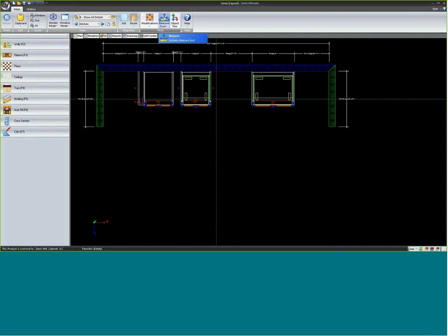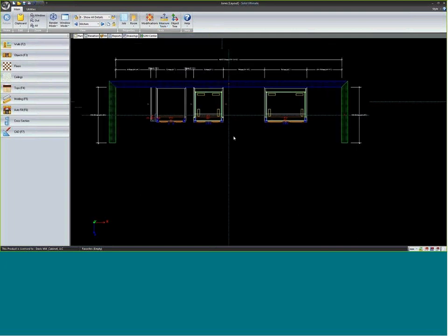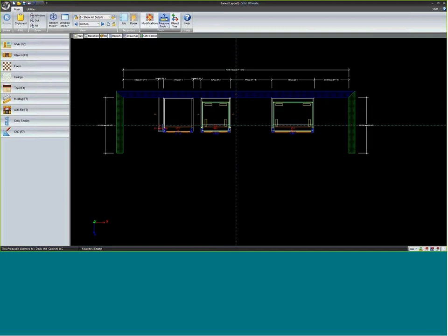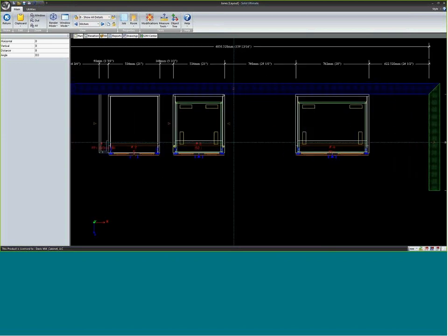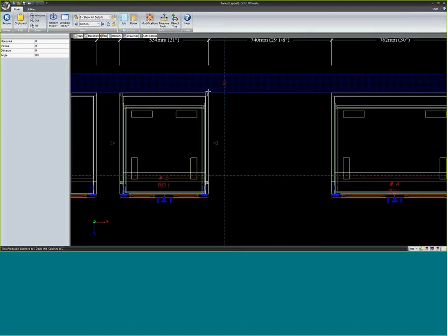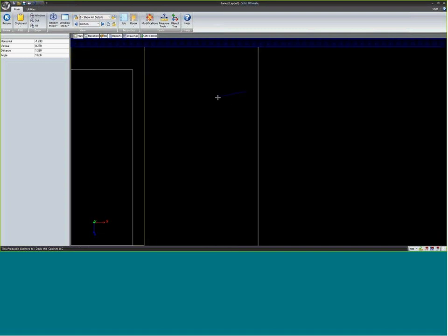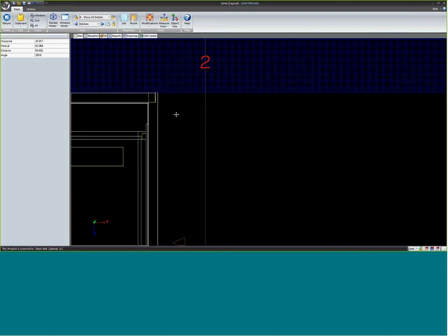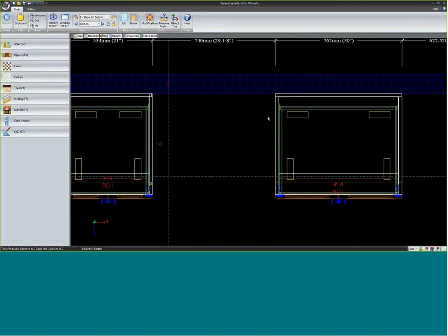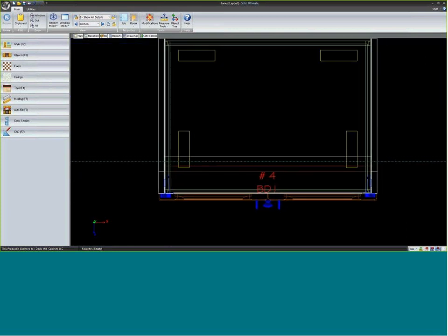So this measure tool is fairly commonly used, though, for just measuring spaces between items. Now, one problem with this measure tool is if you'll notice here, if I'm trying to snap onto the side of this cabinet, there's nothing snapping there. If I click, it's going to be zoomed in. It's not exactly on the edge of that cabinet. So I'm going to zoom back out here. If I wanted to measure exactly between two things, there's a snap mode we want to use. Instead of snap to marks this time, I want to use this far one, which is snap to point. And I'm going to click on this, but as I do, watch closely on the cabinets. Notice right now you see all the lines and things that make up this cabinet.